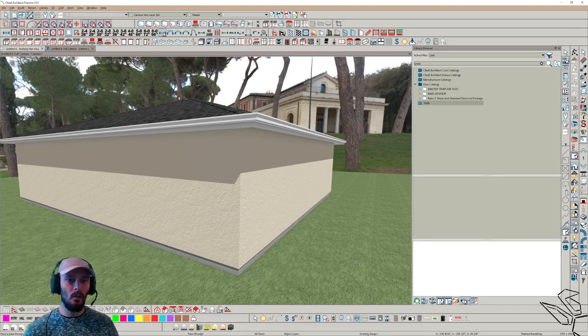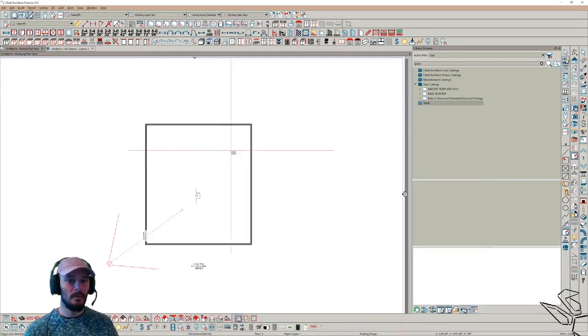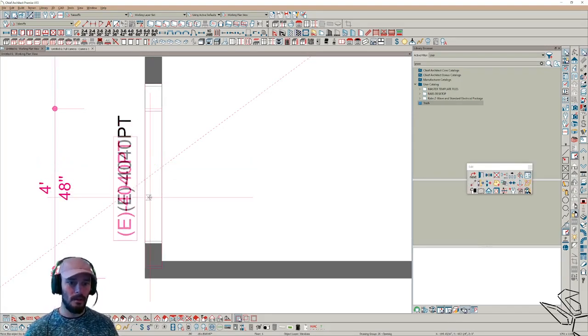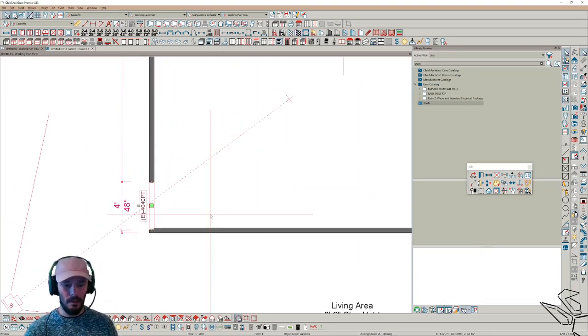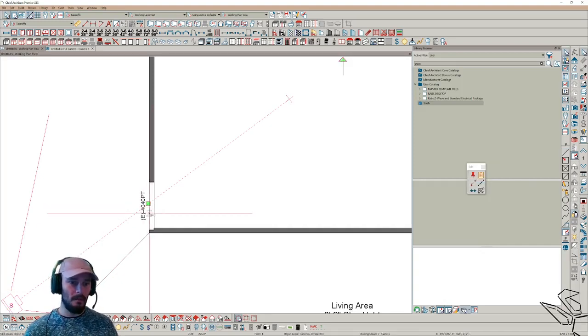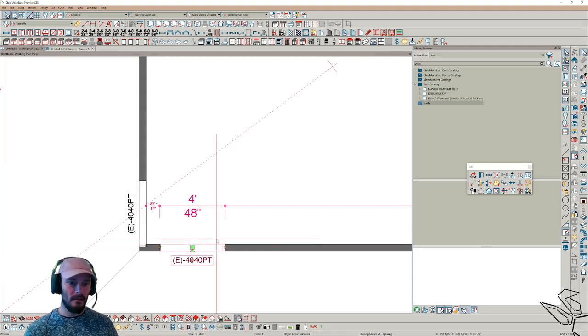So there's a known workaround in Chief for creating zero corner posts, right? Where we're cutting away a wall here. Let's just do this. I'm going to drag this pass-through window, and I'm also going to draw a little inference CAD line. That way I can copy, paste, reflect about center. If I copy the right thing, there we go. Just like that.